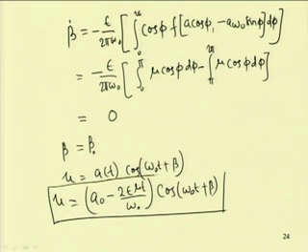So, this is the expression for the response of the system with Coulomb damping. One can plot this amplitude, that is A 0 minus 2 epsilon mu t by omega 0, varying with time. So, one can see that this amplitude varies with time. This is the property in the case of a nonlinear system.